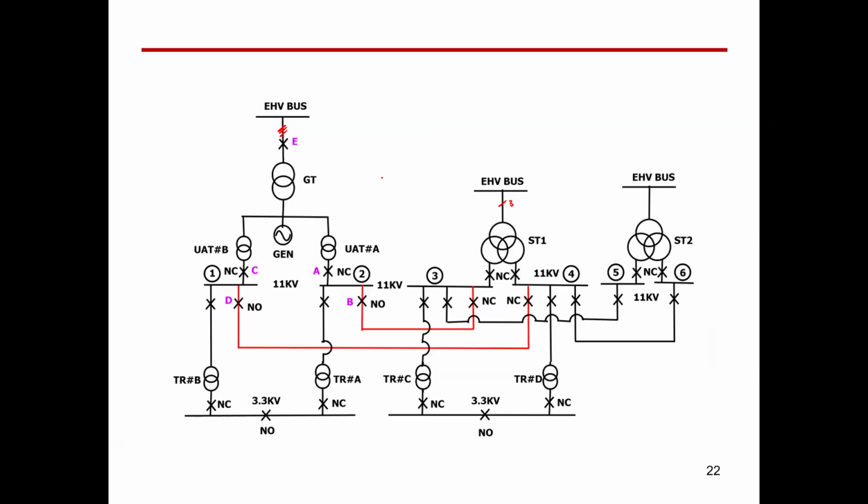And here, as you can see, this is EHV, maybe extra high volt. This is a generator here connected to a certain voltage level. And here we have another transformer connected to an 11 kilovolt bus bar. So this is 11 kilovolt. So this is, guys, called the single line diagram. And on a single line diagram, everything is drawn in single phase and it represents three-phase systems.